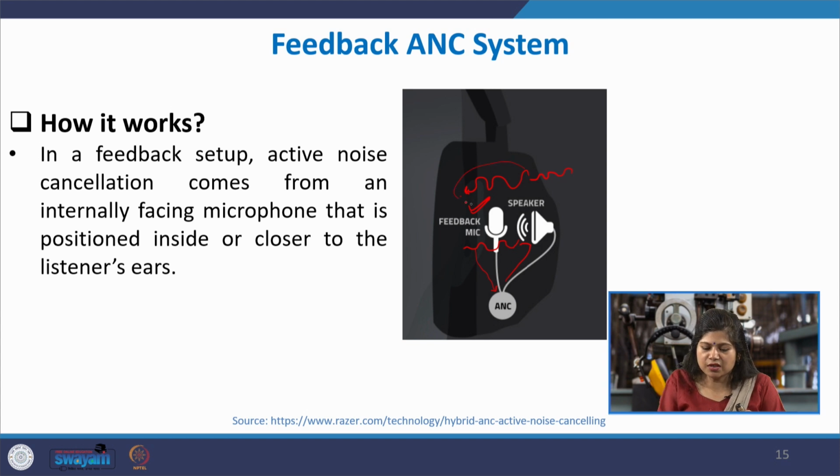So, you measure this reference signal, you send it up, and a new anti-noise signal is created, but by that time it is created and reproduced, a different form of signal has reached the ear. So, which means that here there is always a lag. You first measure, create the signal and generate the sound. So, there is always a time lag. So, if you do not have a steady environment, then in that case this lag is quite visible.